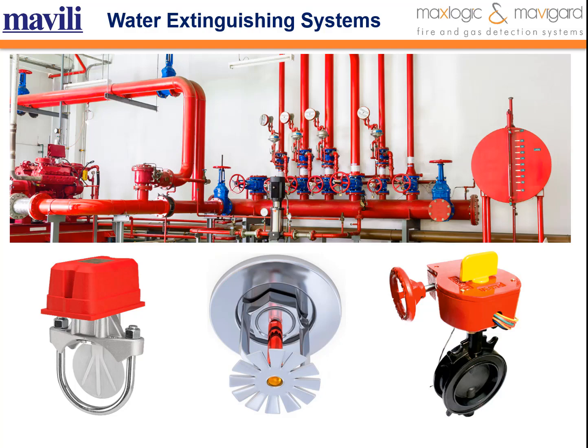The purpose of sprinkler monitoring systems is the continuous control of the main functions of the system. In other words, disruption of these systems may disrupt the correct automatic operation of the system in case of fire. Alarms from monitoring and alarm devices should be mounted on the fire alarm panel in the sprinkler control room or pump room and communicated to the responsible personnel at the permanent control point, on or off-site, depending on the importance of the alarm. The continuity of the connection of the device that provides the automatic transmission of the alarm signal from the sprinkler installation to the fire team or the remote control center with people, and the continuity of the connection between the device and the control unit must be ensured.